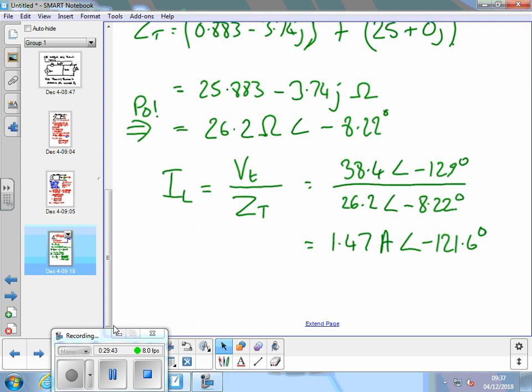The only issue with Thevenin's and Norton's with AC circuits is you're fixed at the frequency. If you were to change the frequency, then the value of the reactive components is going to change, and therefore you'd have to redo the Thevenin's process.